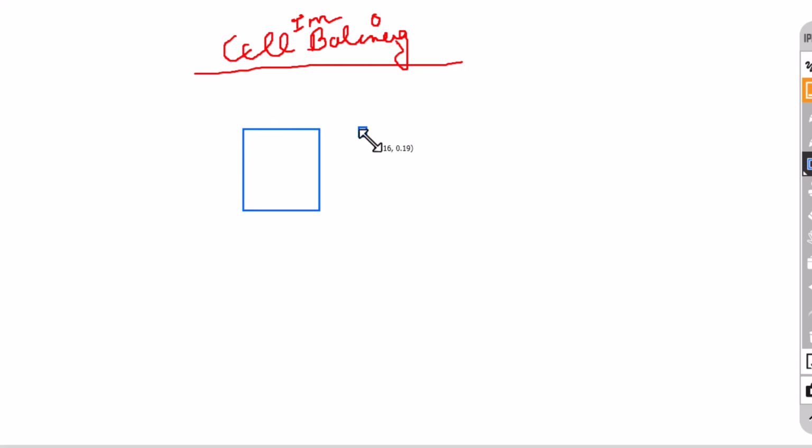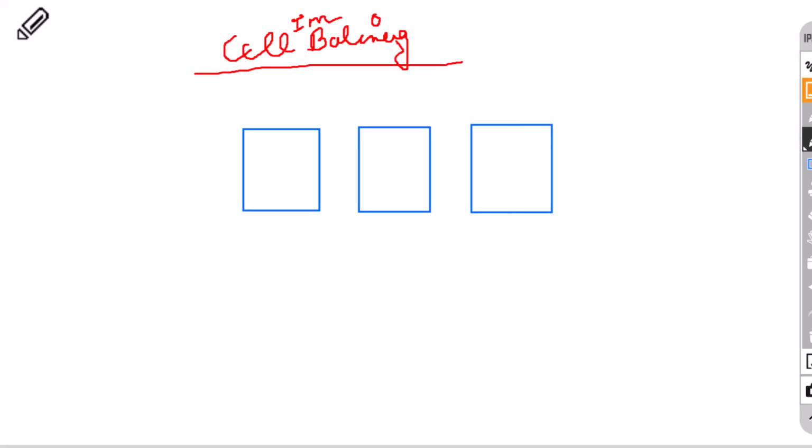It may be 64, 65, based upon the requirement of the motor. For example, Mahindra Electric, they are using 64 cells. Tata will use different. So electric vehicle manufacturing companies use a number of cells in series and parallel.